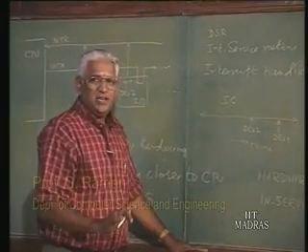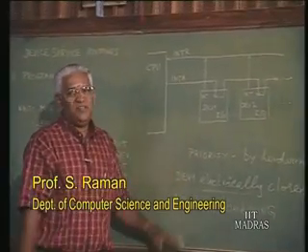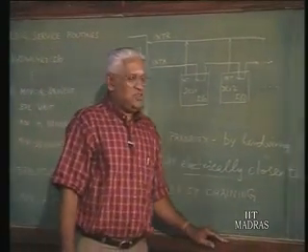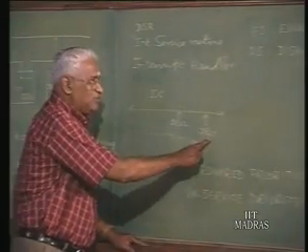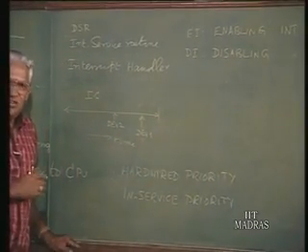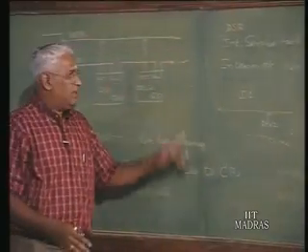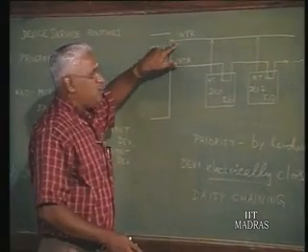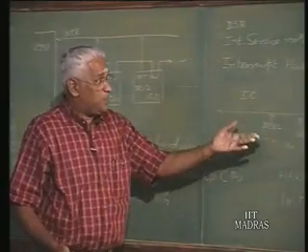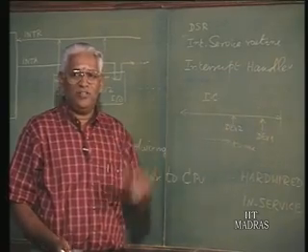No more interrupts will be accepted by the CPU. And the very last instruction of device 1 interrupt service can be enable interrupt, in which case that instruction will be completed, and only at the end of that instruction cycle will the interrupt input be honored. So we can complete the device 1 interrupt service and then respond to anything.